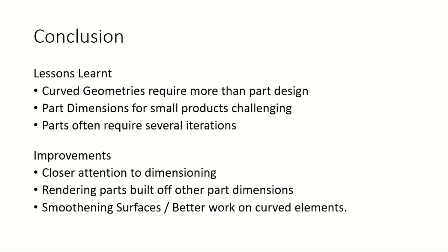So in conclusion, some of the lessons learned would have been that the curve geometries definitely required much more than part design. It required a lot of GSD and a lot of wireframe elements, and they were simply very complex to create. Secondly, part dimensioning for the small products proved really difficult because of the small surfaces we were working with, primarily in millimeters, sometimes dimensions ending up in 0.5 millimeter or 1.5 millimeters.